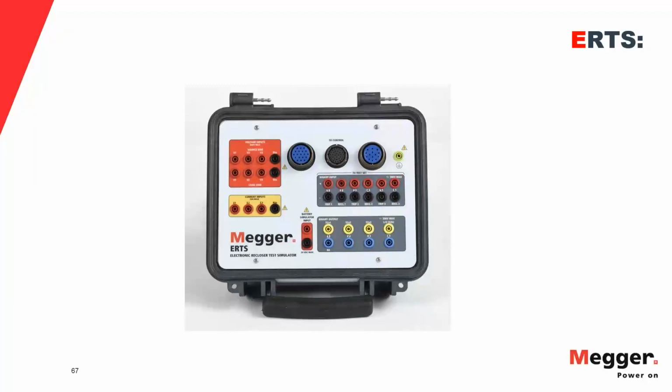And remember, you have the connections to the control, and then on the back of the test set, you have the connections to the tank, right? This is the Megger ERTS. I guess this is the last part of our presentation. It's a unit that allows you to interface with the control unit using a test set, using which you can inject current into these current inputs here, put voltage into these voltage sources here, and those currents and voltages will be fed into the controller via one of these control cables here.